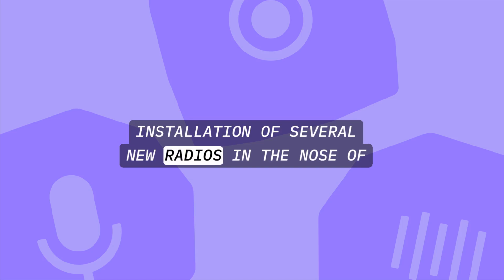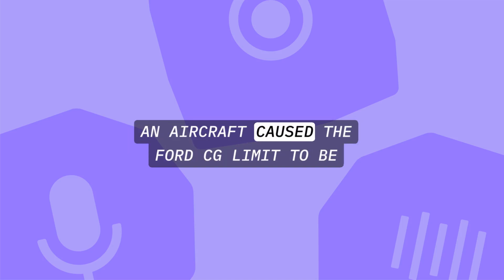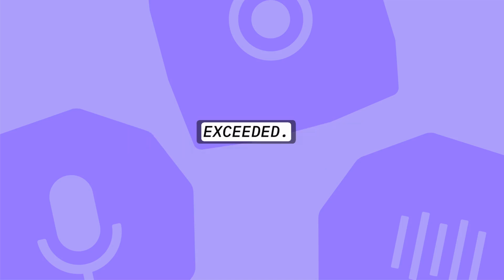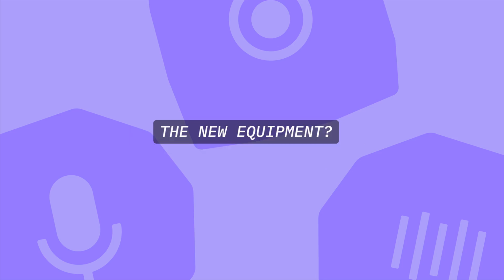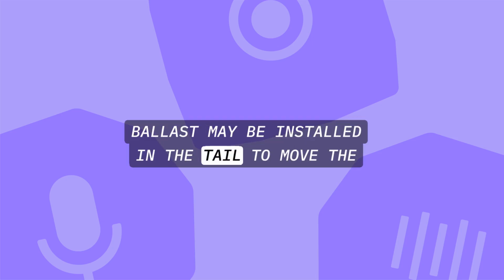Installation of several new radios in the nose of an aircraft caused the forward CG limit to be exceeded. How can you correct this problem without removing the new equipment? Ballast may be installed in the tail to move the CG aft.